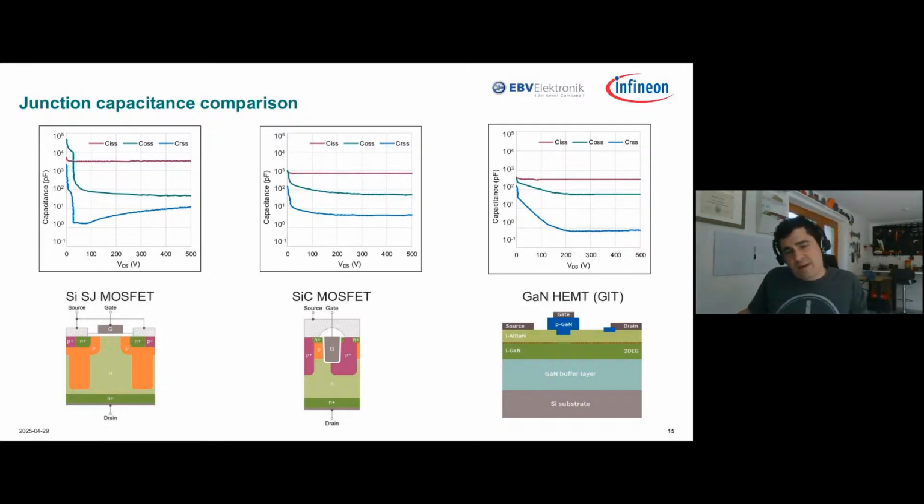Now, silicon carbide trench MOSFETs are similar in that there are some wells, so you have to deplete the regions between the wells first, and then you deplete vertically. There's a little bit of nonlinearity. And again, there's completely different geometry. So for CRSS, notably, there's a bit of a drop-off, but for CISS and COSS, it's pretty flat with respect to voltage compared to these other two.